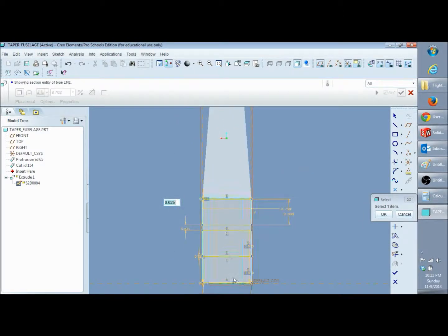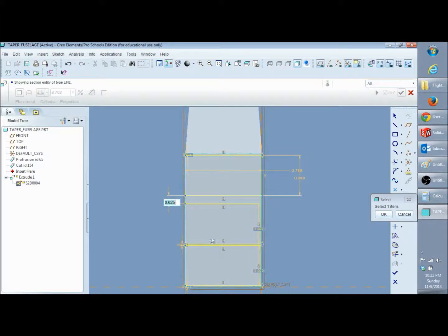So I have 7 dimensions that play for the gap from this edge right here to this bottom edge. So what I mean is you can't have it being overdriven: you can dimension out 6 of the gaps, but you can't have a driven dimension for that 7th gap. So that 7th gap has to be reliant on the other 6 dimensions. Seems like a pretty simple concept, but yeah.